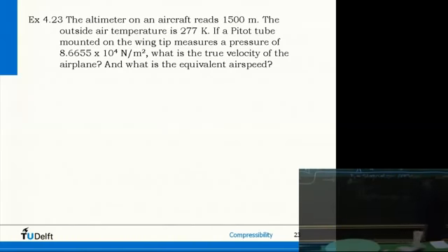We also have pitot static tubes, and that is connecting this one to another with typically a manometer. Suppose you have a channel. You connect this, again a differential pressure gauge now, to this tube. In this way you can measure differences, right? Here you can measure total pressure, and then here static pressure. Why does it measure static pressure here?